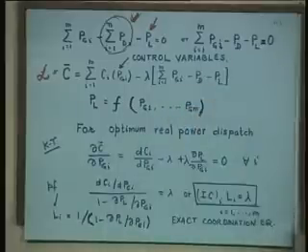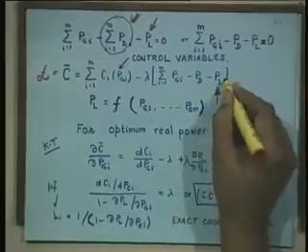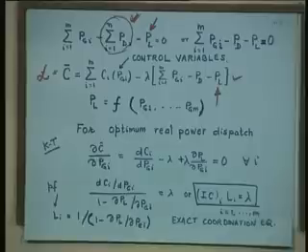And P_L is a new entry to this game. Up to this point we could get away with just writing P_L. Now the time has come when you have to explicitly express P_L in terms of control variables. And what is the control variable here? Only one, P_Gi, the power generation at a given plant i. Such a beautiful practical control problem you would never have had, where there is only one control variable.